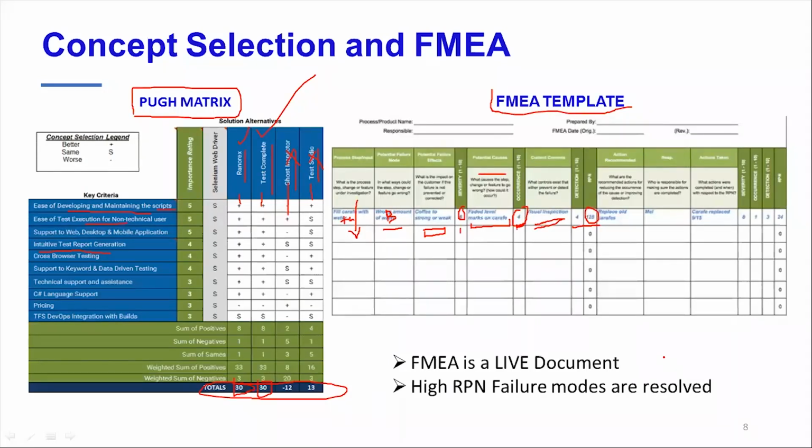Third, what can the tank do? The tank's valve is not working well, so the fuel is not getting filled properly. For the tank itself, you may have 5 to 7 failure modes, and for each you have a respective RPN based on the effect, the occurrence and the detectability.